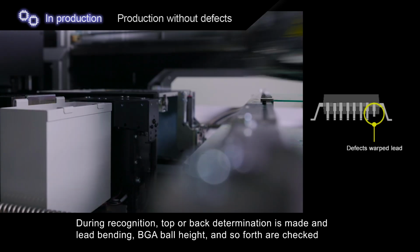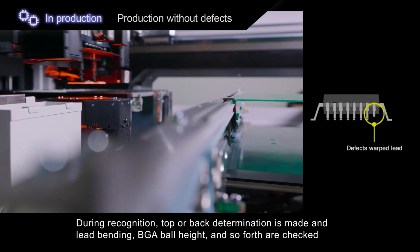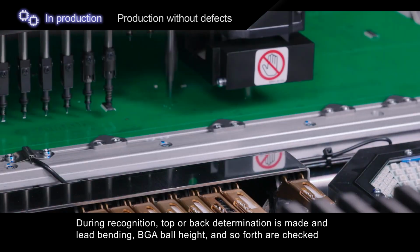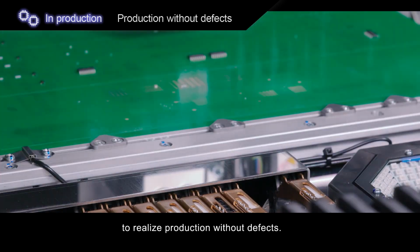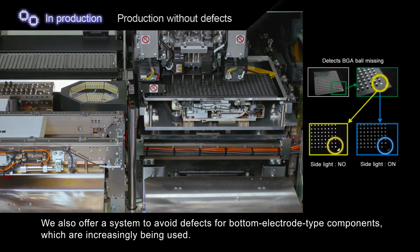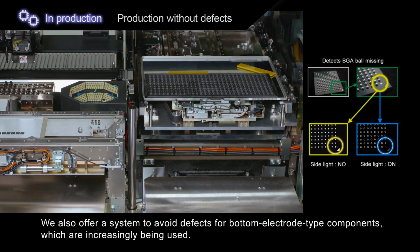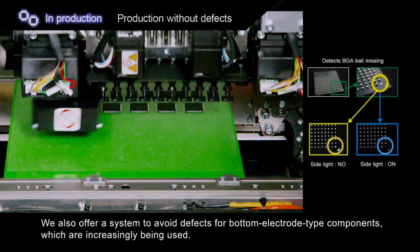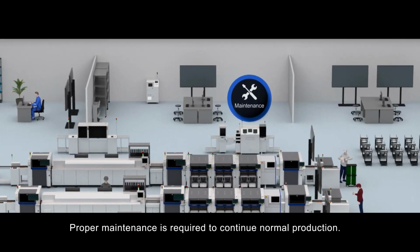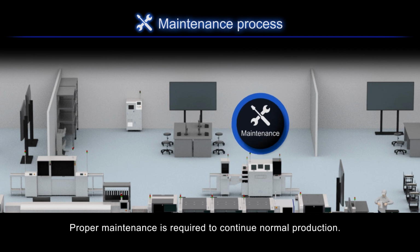During recognition, top or back determination is made, and lead bending, BGA ball height, and so forth are checked to realize production without defects. We also offer a system to avoid defects for bottom electrode type components, which are increasingly being used. Proper maintenance is required to continue normal production.